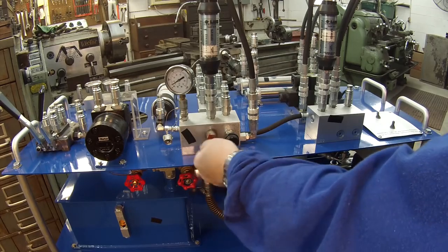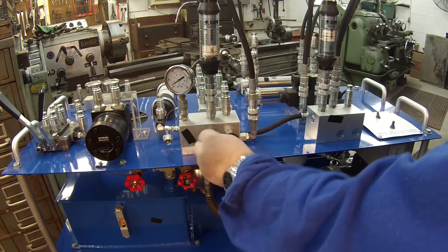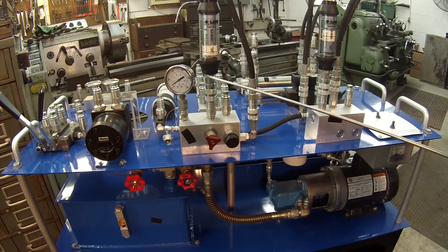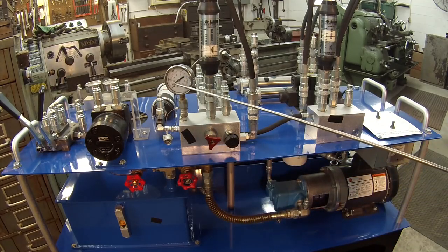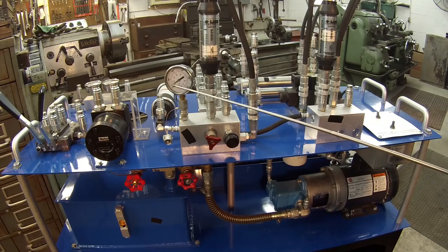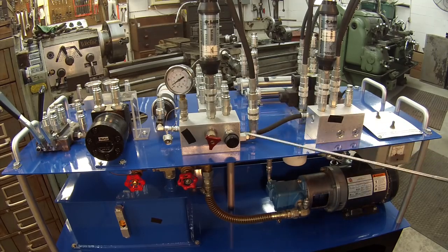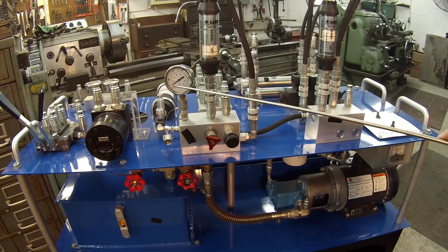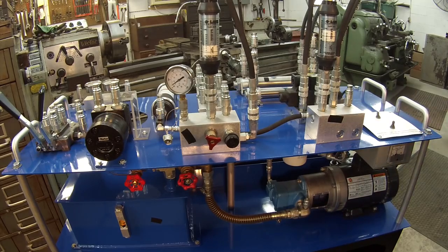And now I'm going to open it all the way up. So the only thing you see right here on the gauge is about 10 psi. And the reason you see that 10 psi is because it's taking that amount of back pressure to push that fluid through these fittings and through this block right here and make it go back through this filter into the tank. Alright, so basically what I'm showing you is pumps don't pump pressure.